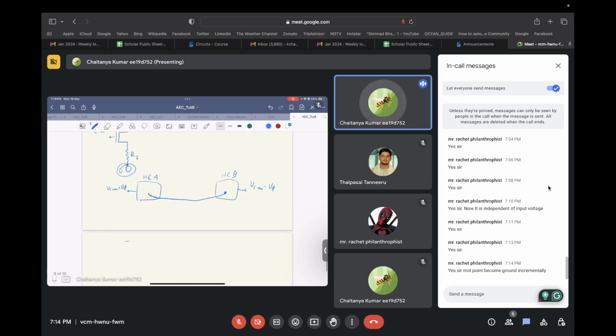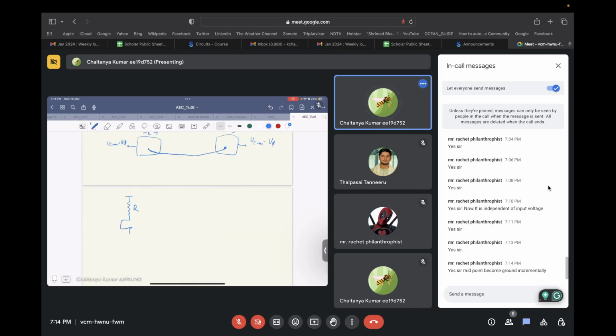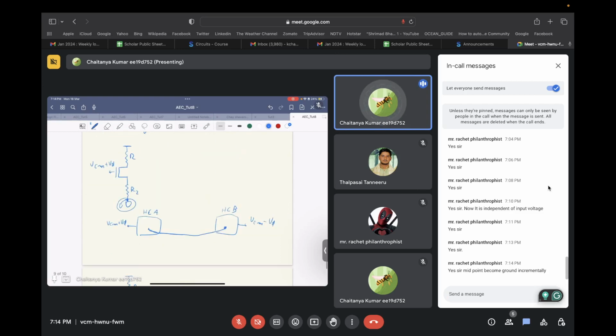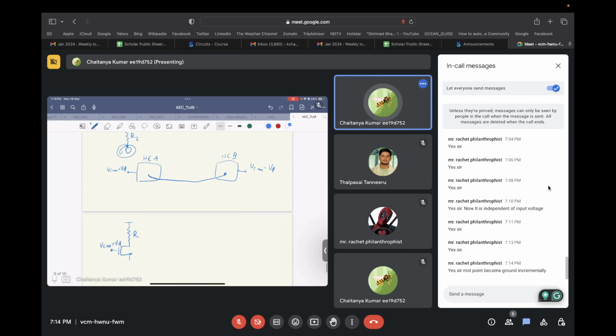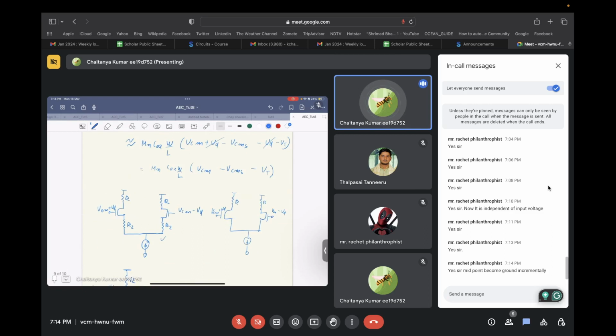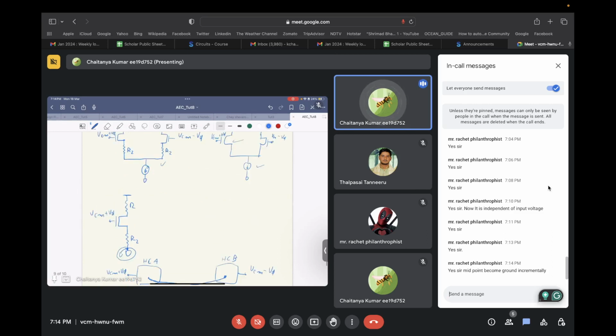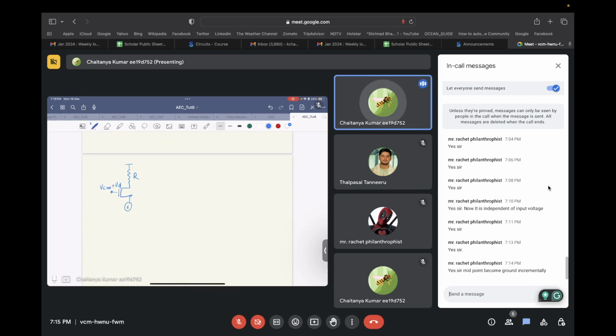So what can be done is as follows. We have a resistance over here, and VCM plus VD over here. We want that in common mode we should only see three stacks: this resistor, this transistor, and this current source. So we put a current source over here, and in common mode we have these three stacks, and we put R2 like this.